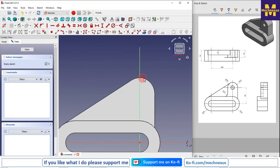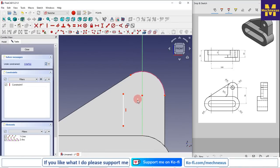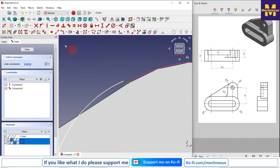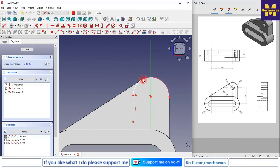Now I will project this arc, so I project this and create a line, and now I will create a 3-point arc, and I create the tangency relation, and in the same way I will merge these 2 points and create the tangency relation.